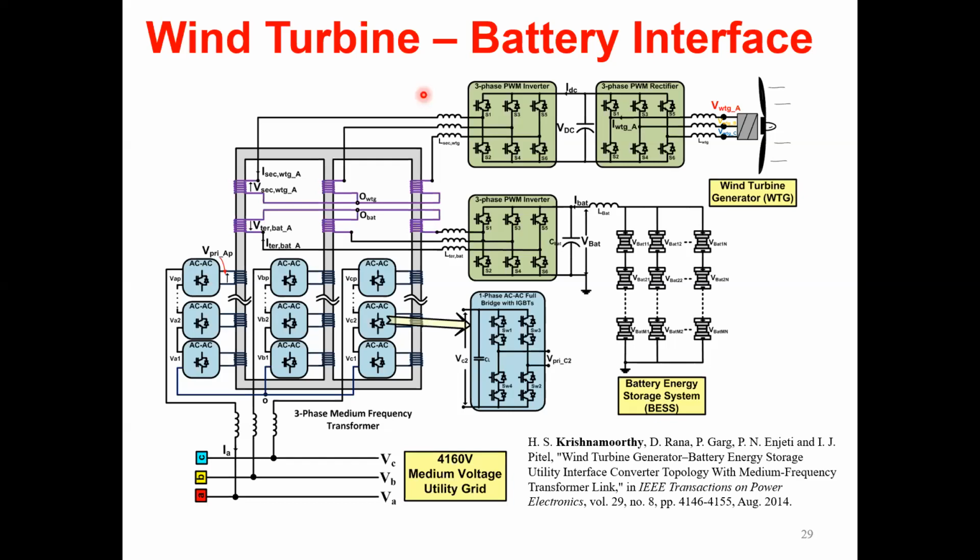So here is the figure which I'm talking about. If you have an AC to AC converter, as we discussed before, this is an indirect AC converter, using a medium frequency transformer, and then you have a rectifier, and on the secondary side, you create a medium voltage DC, maybe plus minus 20 kV. This is for a single wind turbine. You will be able to place this at the top of the wind turbine itself because the transformer size is much smaller. So we can avoid this platform that you see here and take this converter onto the wind turbine itself. We may still need this, but at least we can eliminate one complete platform. So it will make it much easier. That's what we had proposed.